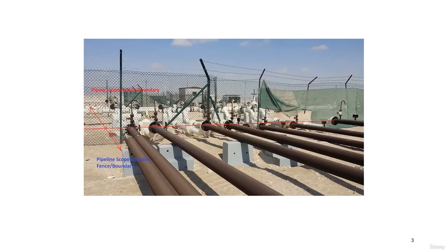So here we are mainly considering the oil and gas industry. So the piping part will be designed based on ASME B31.3, whereas the pipeline part, if it is a liquid pipeline, it may be based on ASME B31.4, and if it is a gas pipeline, it may be based on ASME B31.8. So at these interfaces of the flanges, normally the demarcation exists,